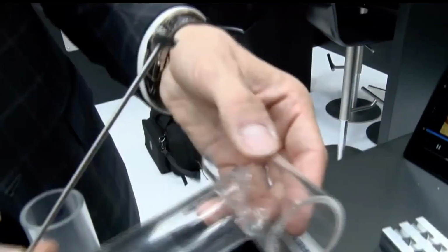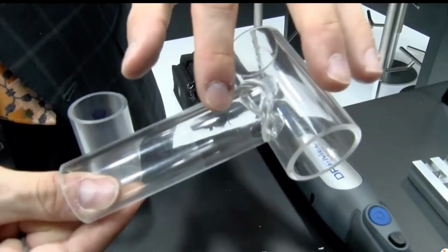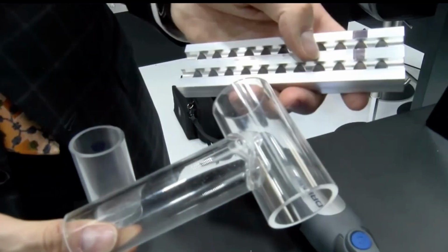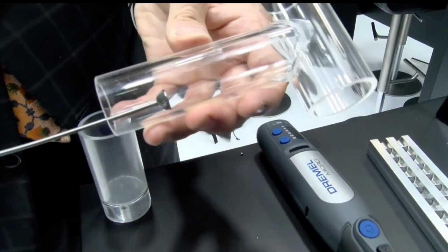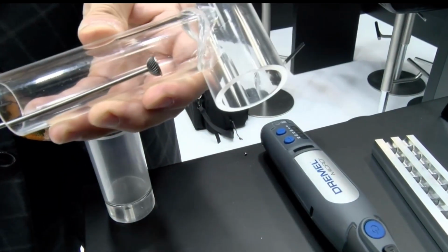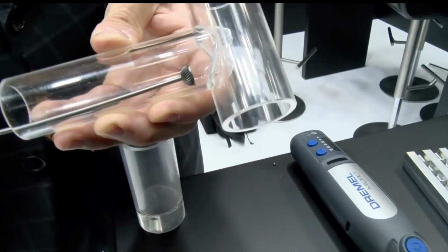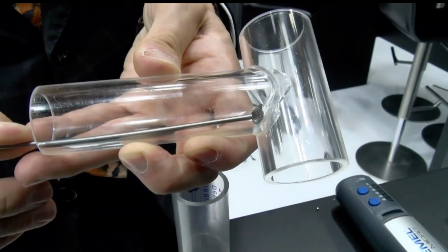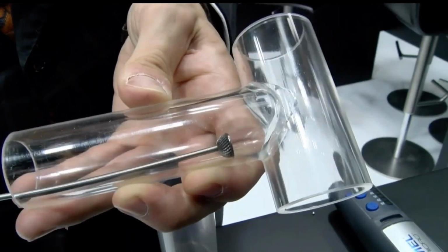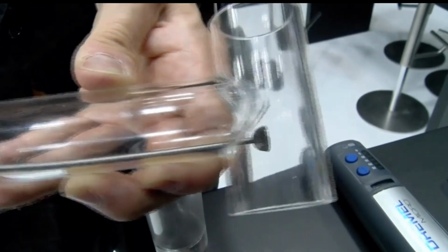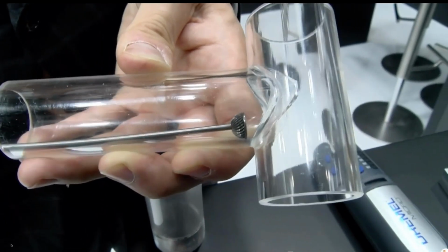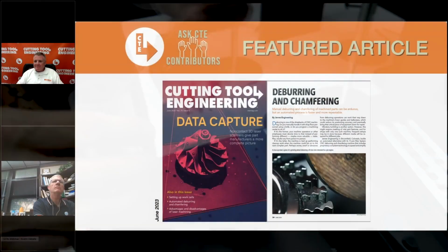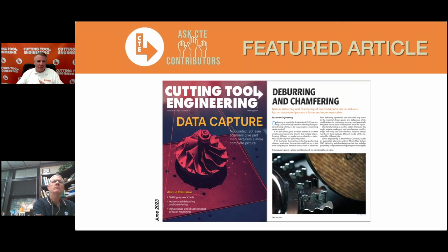So here the geometry of this intersection, whether it's a T fitting in the hydraulic fitting setting or it's a manifold, it's really the same geometry, one hole drilling into another. With this flexible shaft, we're going to preload the tool against the wall, and anytime we're inside that hole, we don't do any damage to the wall. Only when the cutter is going to reach the edge, then it begins to cut. And because we've preloaded and flexed that shaft, it's going to automatically pop in there. So here, this is the final condition where the tool is fully against the wall. And when we're inside the hole before we reach the edge, then we've got this bent condition. So I just wanted to show that to you.